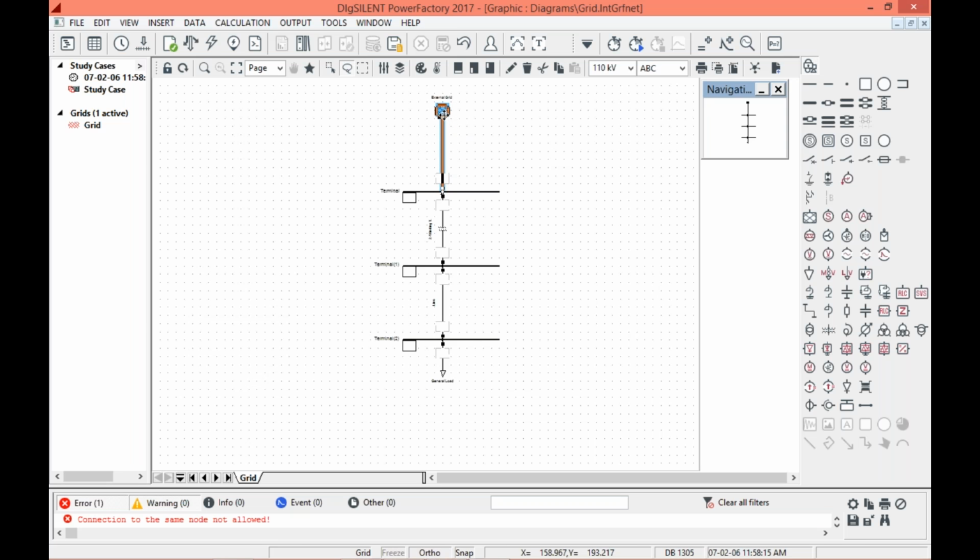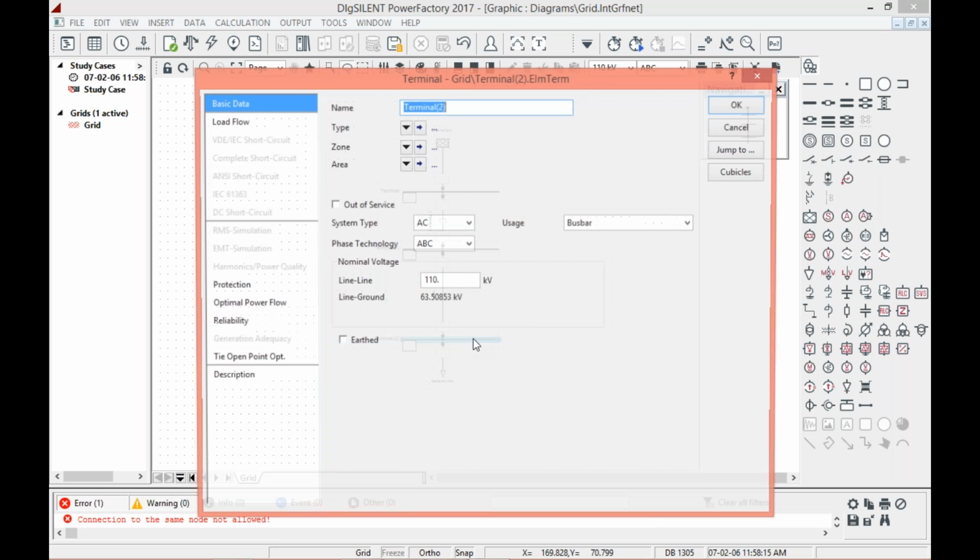Click on this, and after that drag downward. Click on the mouse. When this cursor appears, it means you can drag now. So just drag here. See, the network reduced. When you want to decrease the size of the transformer, you can't decrease the size of the transformer itself, but you can decrease the spacing between the two buses, and you can do it by clicking on this and going nearer to bus 1. With that, the transformer size will reduce, and the same with this.